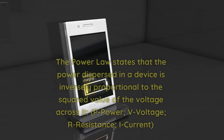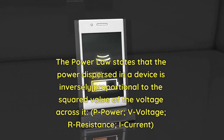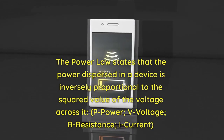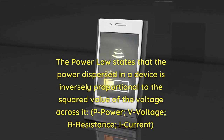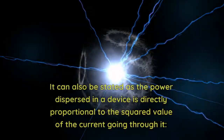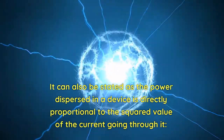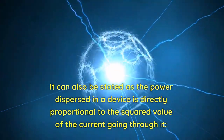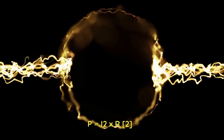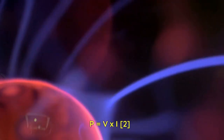Power law. The power law states that the power dissipated in a device is directly proportional to the squared value of the voltage across it, where P is power, V is voltage, R is resistance, and I is current. P equals V squared over R. It can also be stated as the power dissipated in a device is directly proportional to the squared value of the current going through it. P equals I squared times R. The power law can also be simply stated as P equals V times I.